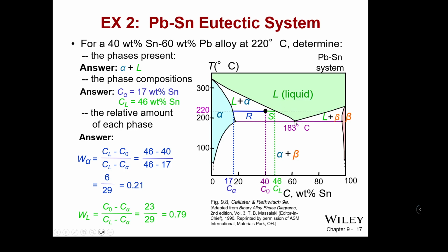So above the melting temperature, the majority of it in terms of mass is liquid. We would expect that if this is above that eutectic melting temperature, as we're getting really, really close to melting. So that doesn't mean that the point is far, far away. That temperature point is not far from the liquid. It's below the completely liquid line, but it's pretty close. So we should expect the liquid to be a higher percentage, and that makes sense.